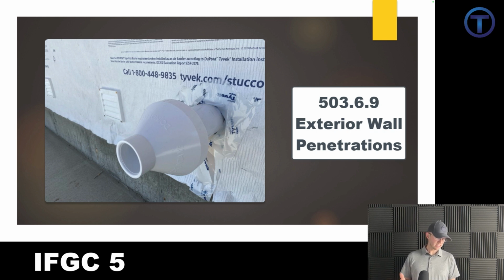It says a gas vent extending through an exterior wall shall not terminate adjacent to a wall or below eaves or parapets except where provided with section 303.2.3 or 303.3.3. There are some exceptions, but generally you don't want that exhaust pushing out under the eaves. You don't want that exhaust coming out right next to another wall where it could do damage to wall surfaces. So there are certain distances, and we're going to look at exactly where you can and cannot put vents here in just a little bit.